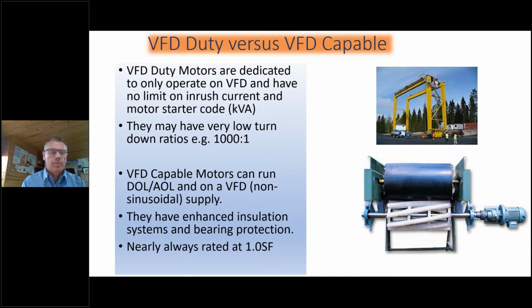Now, a VFD duty motor is a dedicated motor that's intended to only ever run on a VFD. The characteristics of that motor are not designed to be connected across the line. I've used an example here of very low turn down ratios, or hoists and cranes, where you may have to position and hold that load either indefinitely or for 5 minutes with no rotation. A normal motor will burn out. A VFD capable motor has features built into it to withstand and continue to hold that current in a stationary position.